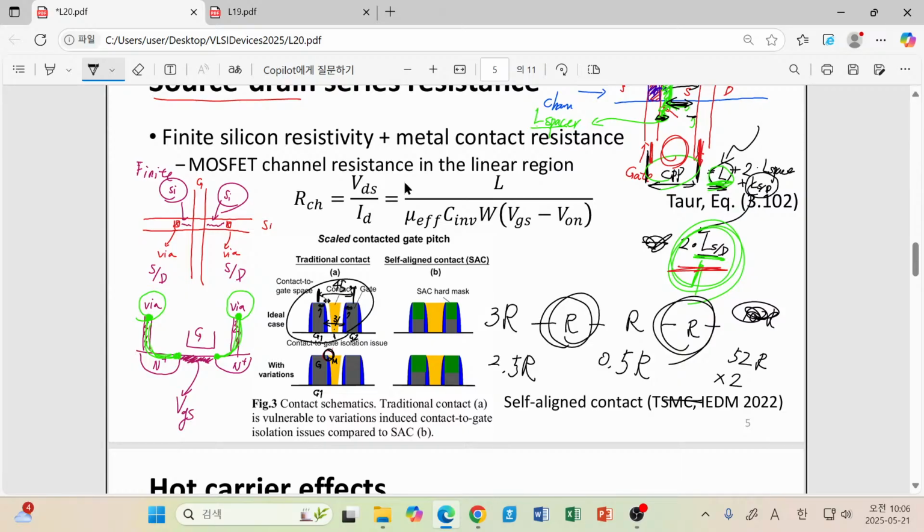So simply speaking, our internal transistor is already very good. But the point is, in order to fabricate it, we must introduce this fixed resistive component, and without improvement of this resistance component, we cannot further increase the performance.